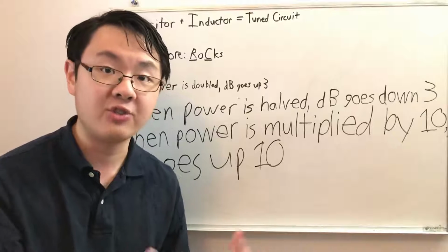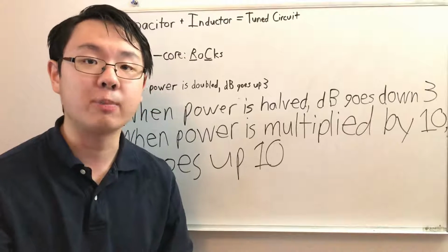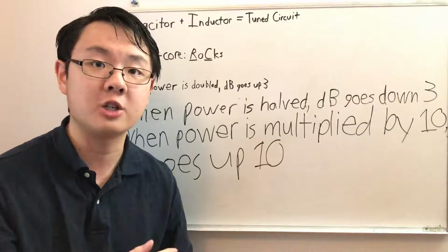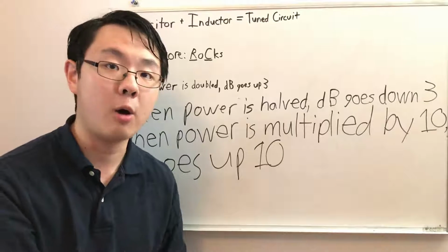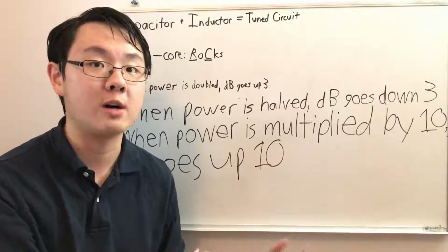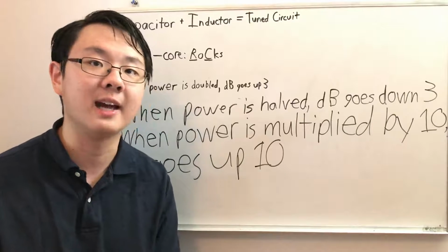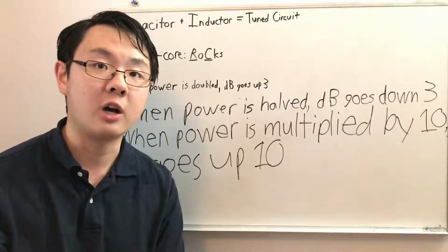And if you see this, that means it's a cold solder, and this is a poor soldering job. You didn't do a good job. The circuit isn't going to work well. The component isn't really connected to the circuit board very well. It's not going to work, and you probably need to do it again. So anyway, that's what a cold solder is.